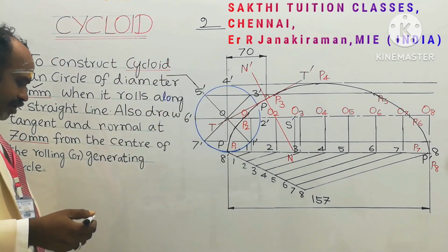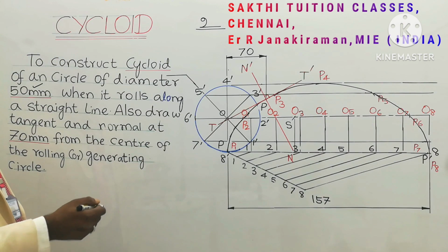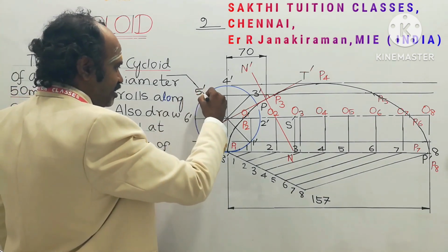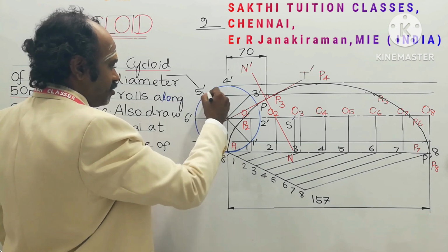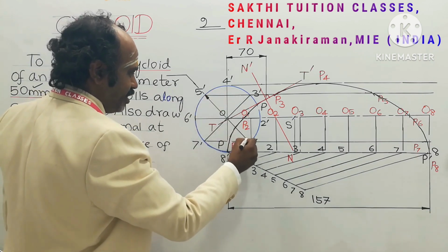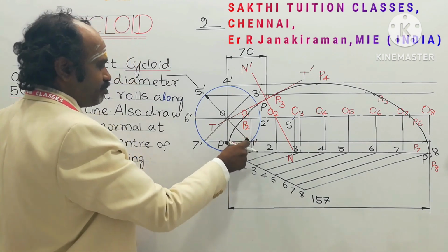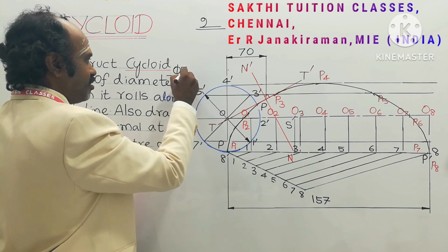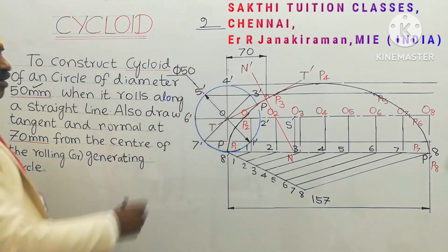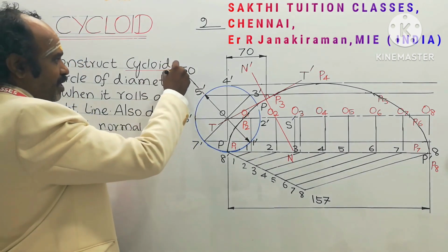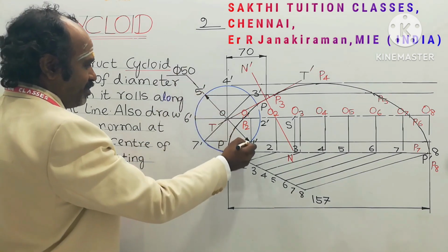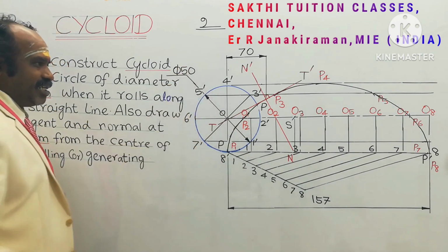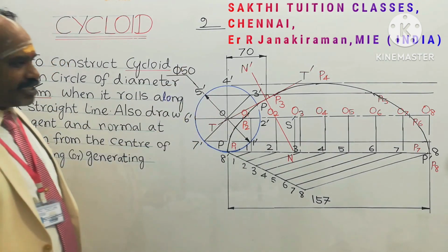Understand? So now I am going to provide the diameter. The diameter of the circle is given as 50 mm. Provide two narrow arrowheads and shade them like this. This length of the line is the diameter, that is 50 mm, from this point to this point. It is marked as phi 50. Phi is a notation used to indicate the diameter of the circle. So this length is the diameter, and it is written as phi 50. Understand? So next, is anything else missed?